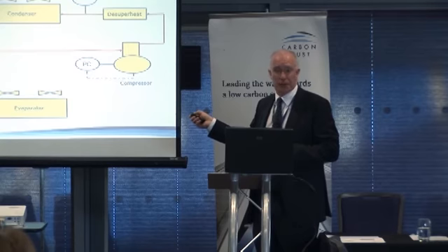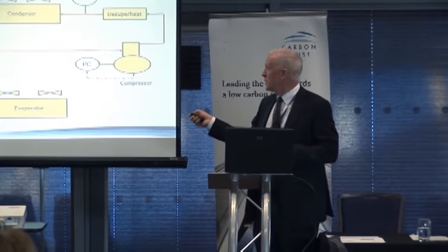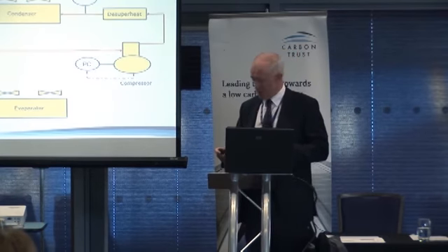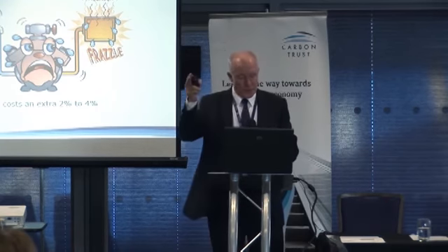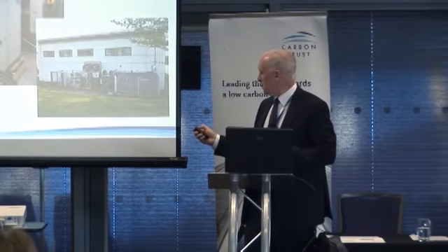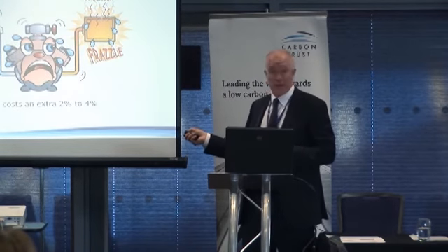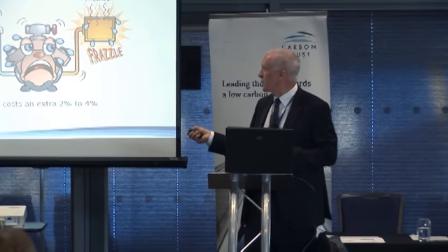So if you have refrigeration, we are very concerned about minimizing the difference between the lowest temperature and the highest temperature at the condenser. That's the key in terms of energy efficiency, for all the reasons we spoke about earlier. So what we're trying to do is increase the temperature of our evaporator as much as possible, and that will be achieved if we elevate our temperature in the computer room to 24.